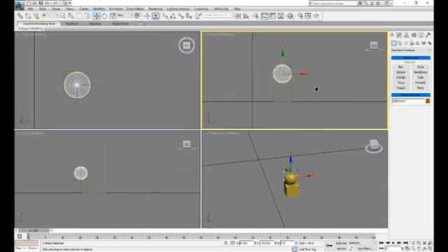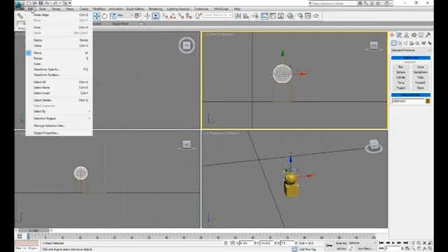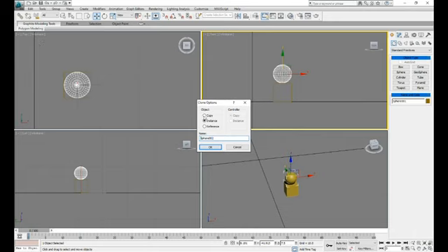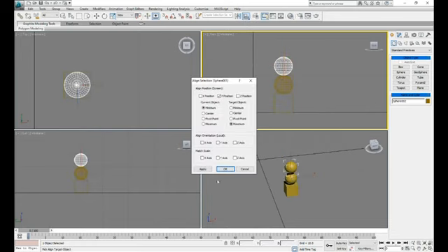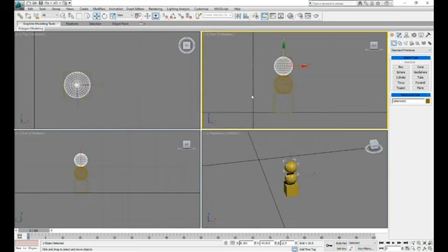Now, class, I want to create a baluster, as I have told you. A baluster is just a support, like the railings in your stairs. Should I create another sphere? Okay, no need. What you will do is click here on the right side, edit, clone. The meaning of clone, class, is copy. Then you will say copy. Okay. And then align it again. Check what happened. See, you have two objects now.